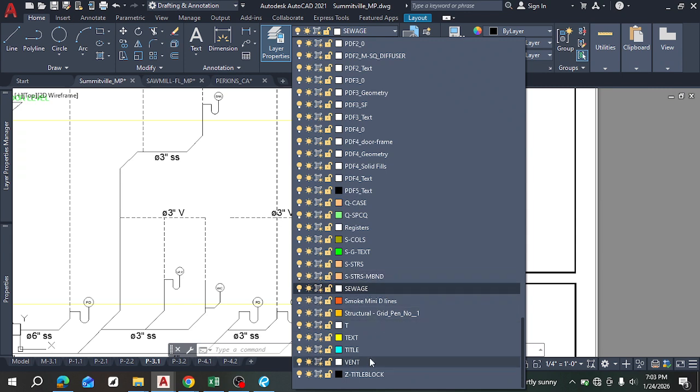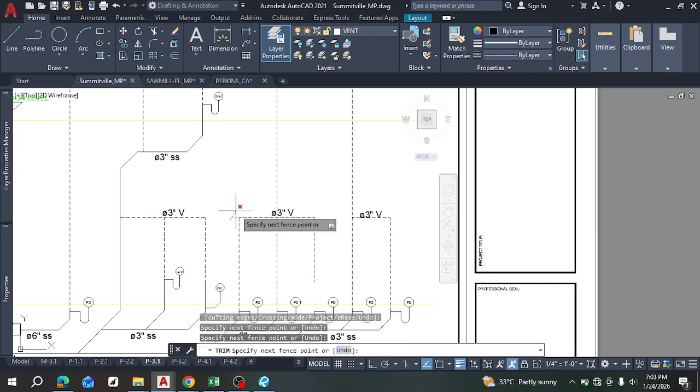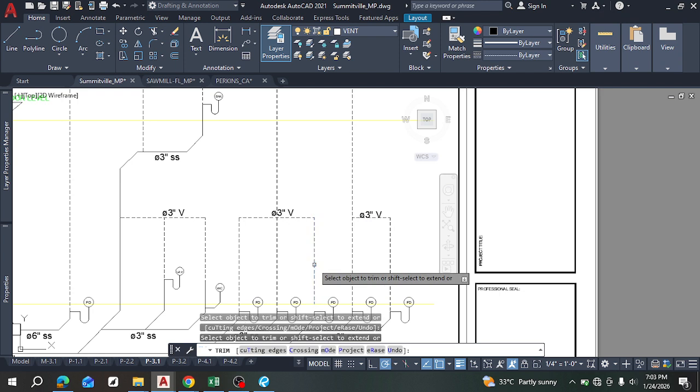Okay, layer. So now every line we draw will look like a vent line. So this is now what it looks like, right? And then I extend this one with the shift key. Extend it again. Good. Now to be on the safe side, this is going to mean that there are vertical pipes running, and the vertical pipe goes up to any distance of the contractor's choosing, and then there's a vertical pipe connecting them for more efficient venting, right?